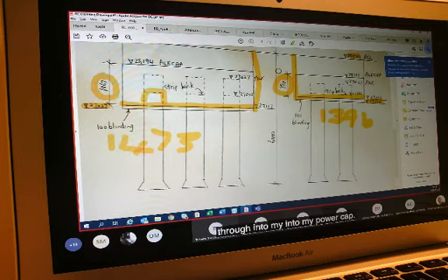And I have to deduct the protrusion of the pile into my pile cap. It will be 0.24 by 0.24 by 0.08, as it comes down to the same height that it protrudes into my pile cap, and times pi times 4 of them.